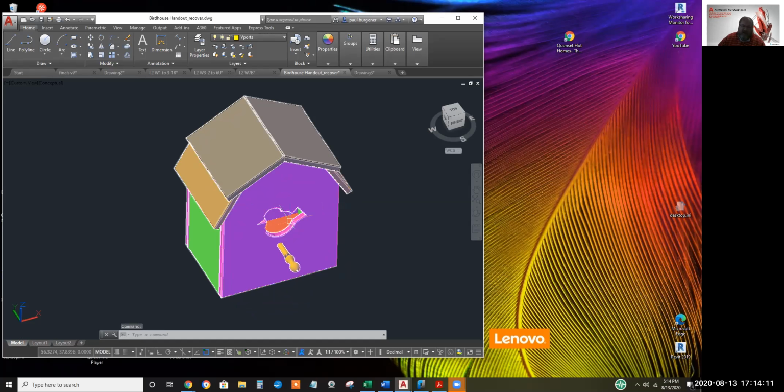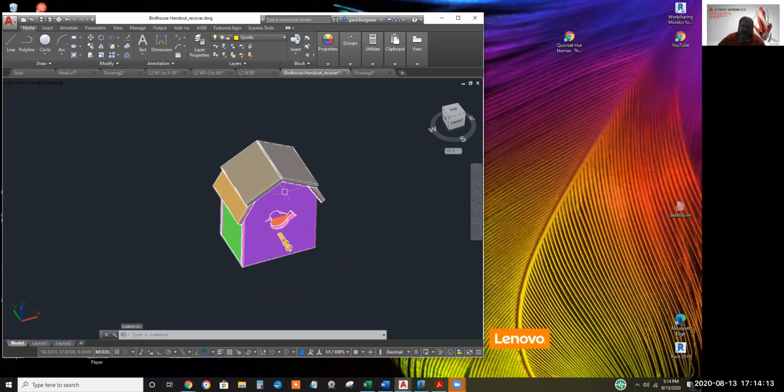Now, AutoCAD's smart enough to know the X, Y, Z of this object, and with that, and maybe the weight typed in, you can do list and trim calculations with attributes. Your diesel engine has attributes, your reduction gears have attributes, and with a spreadsheet you can calculate how much the thing will list when you launch it.